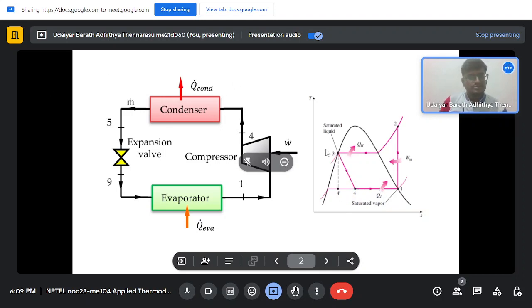So after cooling in the condenser, you pass the fluid which is in liquid form through the expansion valve. So this will cause the fluid to expand, and then the fluid which is coming out is at a lower pressure and corresponding evaporator temperature. Now the fluid is in two-phase region. This is passed through the evaporator. So now the evaporator will pick up heat where you want to cool. From there it will absorb heat, and the fluid is boiled, and it will convert to vapor phase. So then again you pass it through the compressor.